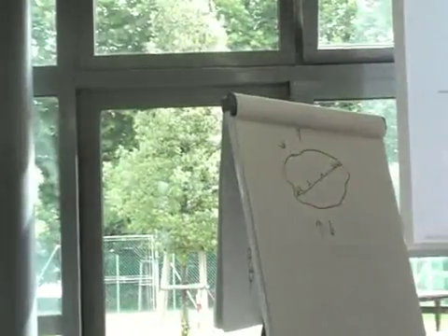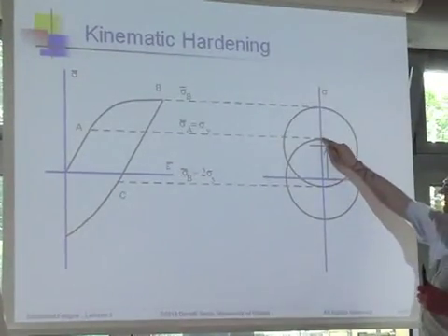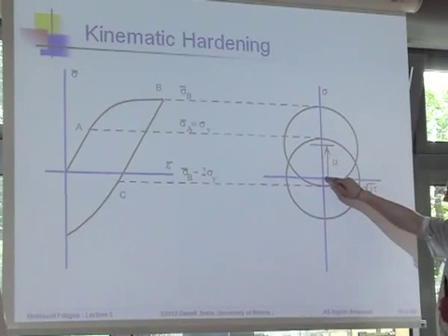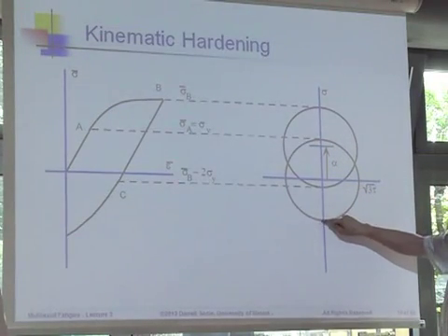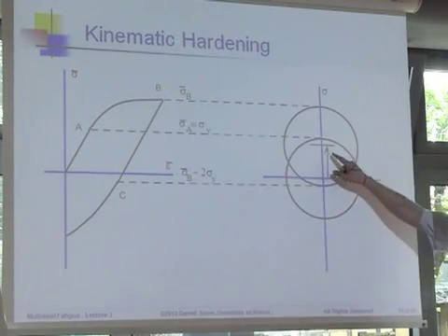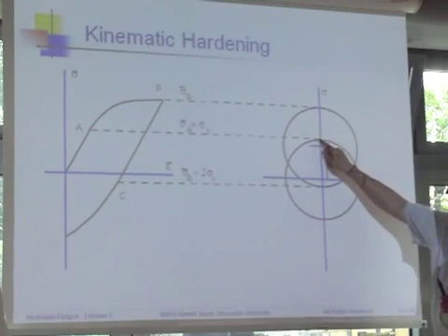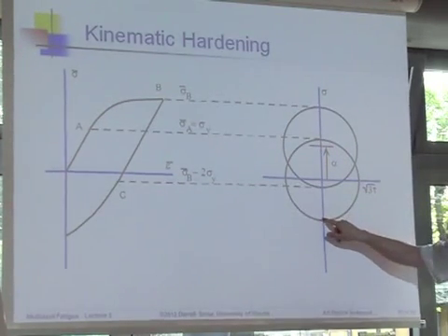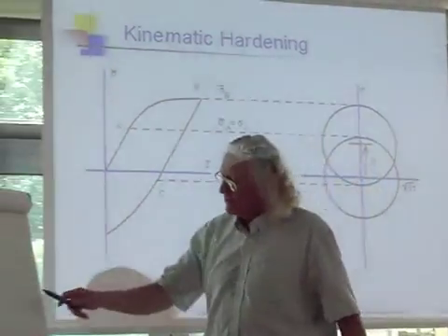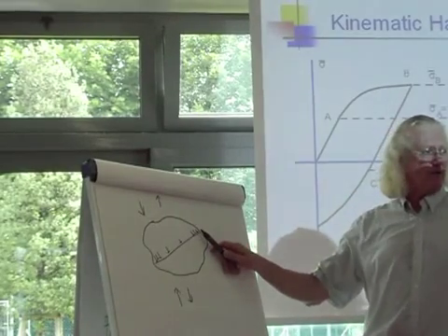And if I look at that on my little diagram and said, okay, fine, if I load something in tension, I'm going out in this direction to this spot. But I could just as easily have gone off to this spot. Right? But look, this represents the elastic range, so that says I could go from here to here, and I'd have twice the elastic range. Because first, I could load this and move all the dislocations in this direction, right to the yield point.